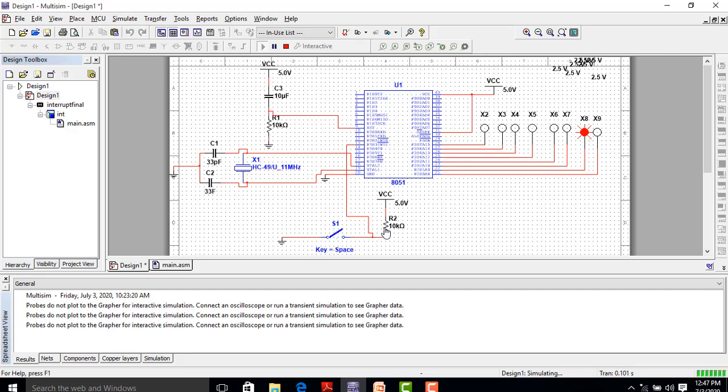Press it once again. These both should become 1 because it will be 3 in binary. Agree? 3 interrupts have occurred. Now 4. Now what will happen? We'll move to this bit, right? So this should become 1 and this should become 0. So it will become 4. Let's do that. You can see that. Move again. You should get 5. 5 means 101. This way.